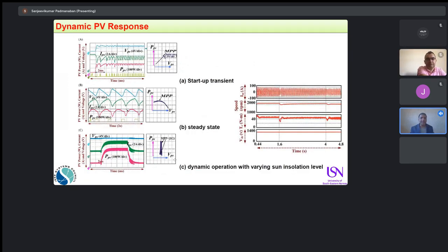And this shows more dynamic behavior in real time, because particularly in photovoltaic systems, this is the voltage generated from the photovoltaics, which are obviously semiconductor devices, and huge subharmonic oscillations are generated, and obviously we will have large oscillations in the current and power. This is a realistic figure of what we obtained from the photovoltaics. From the photovoltaics, we are also looking very closely at the variations of these currents and powers, how much they deviate. But in overall power regulation, under irradiance conditions from minimum to maximum and then to minimum, we are getting very smooth power regulation with a constant power delivery to the loads of induction pumping.